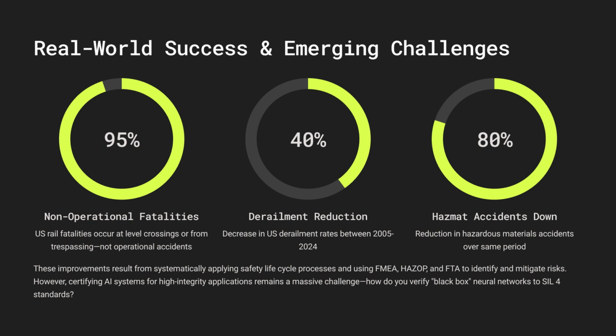Auditing. They review the main contractor's safety plans. They audit the hazard analysis activities, the PHAs, SHAs, HAZOPs. They scrutinize the evidence backing up the SIL claims for critical functions. They check the completeness and rigor of the project hazard log across the entire project lifecycle. They act as the independent check, verifying that the developers have correctly followed the required CENELEC standards and that the documented safety evidence is robust, complete, and convincing. Their final stamp of approval is usually essential before the system can be certified for passenger service.